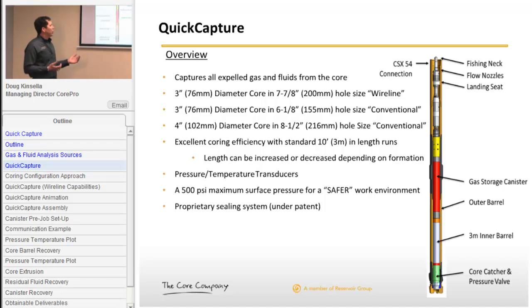One of the main problems, if pressure core worked, it came to surface, and we had to take that core and bleed it down eventually to atmospheric pressure. So we bring a core to surface. We had to design a set of tools that were extremely robust, that could handle maybe 10,000 psi of pressure. In doing that, we ended up cutting a small core, inch and a half diameter. So we thought just outside the box a little bit, and we said, if we're going to bleed it down on surface, instead of bleeding it down on surface and bringing this methane-filled bomb, why don't we bleed it down on the way out of the hole?